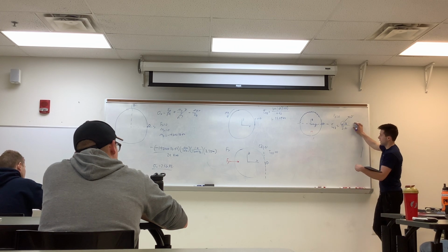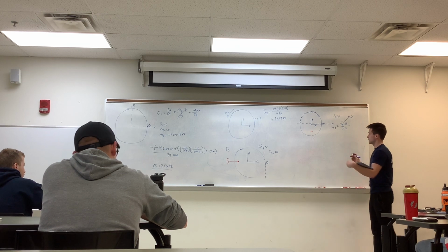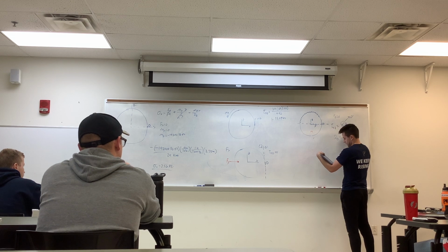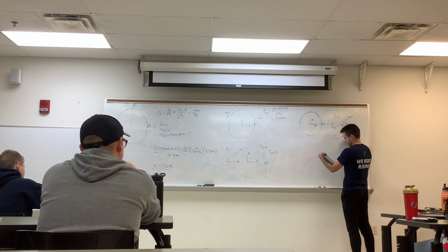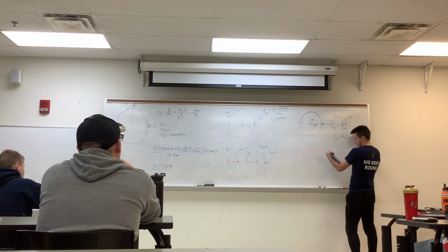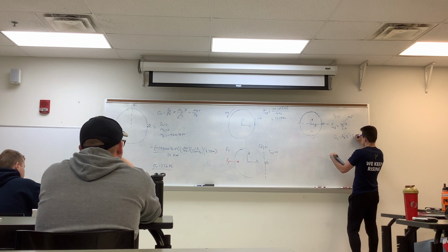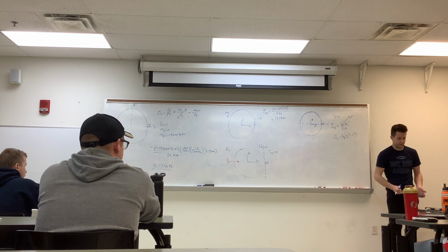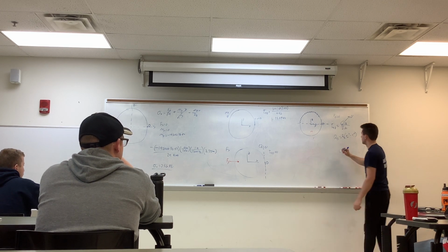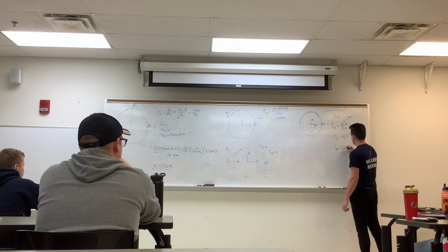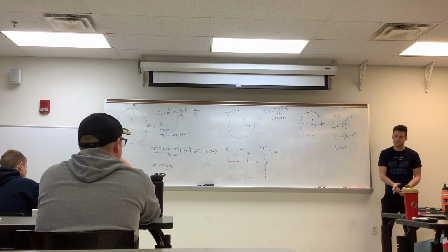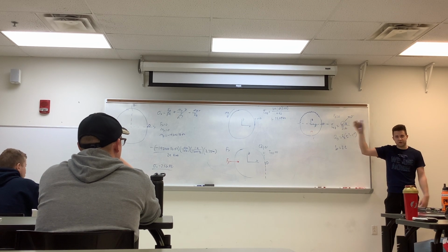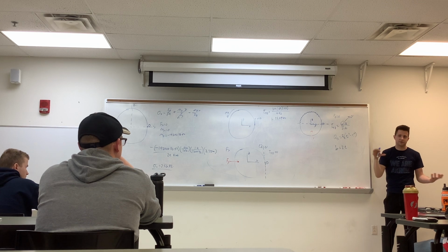But if we wanted to figure this out, like say this shearing force was some positive number, Q at D was equal to 2/3 r outer cubed minus r inner cubed, and you can get a value from there and calculate everything else out. And then the base b just happened to be double the thickness because it's a hollow tube. Just to help clear things up here, make sure at the end you combine all your answers together because I want to see them all together here.